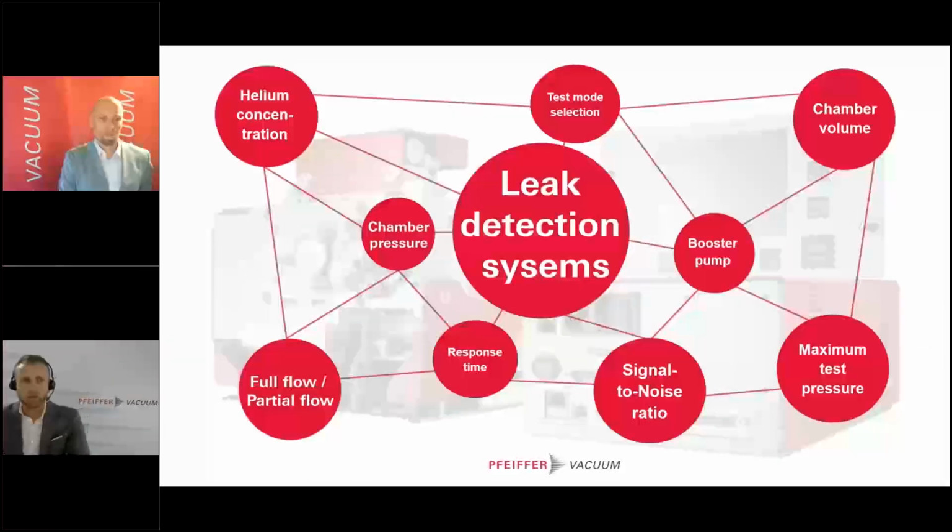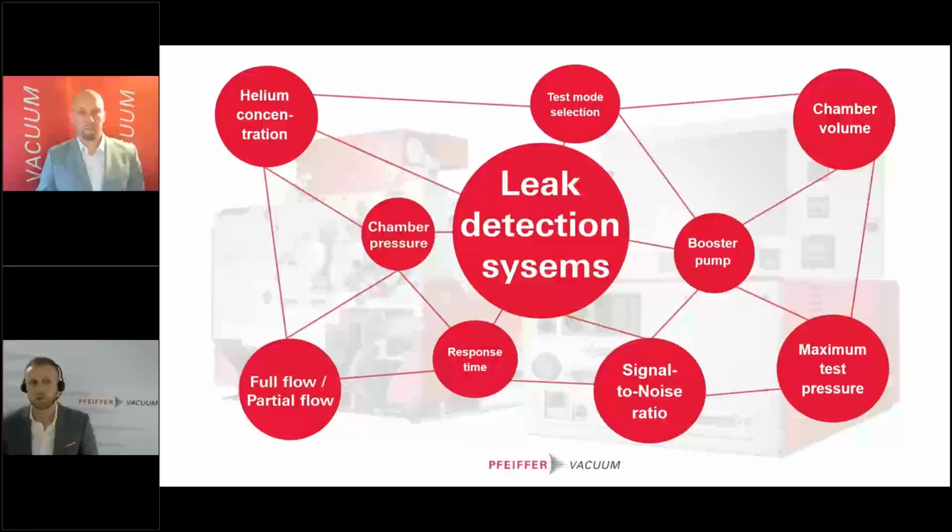Also here you see several different contributing factors which we all need to consider. This is just an extraction, I would say, of the different factors that need to be considered when you are laying out a leak detection system. So whether you are talking about the helium concentration, the full or partial flow, or the usage of a booster pump, your chamber pressure and your chamber volume, the test mode selection and the response time, signal to noise ratio, and the maximum test pressure. These are all factors that need to be considered.